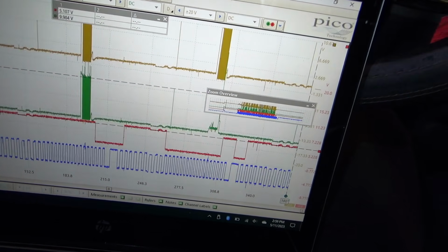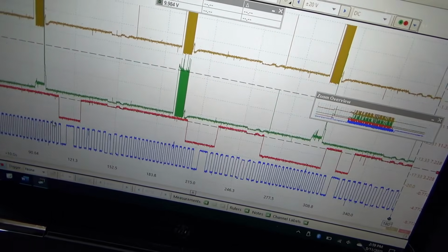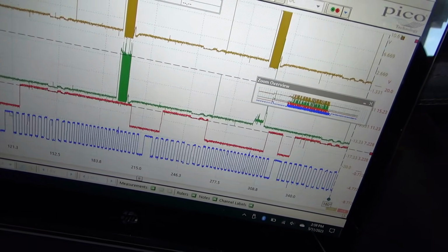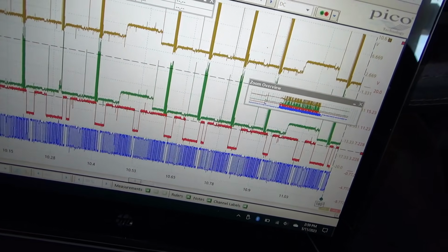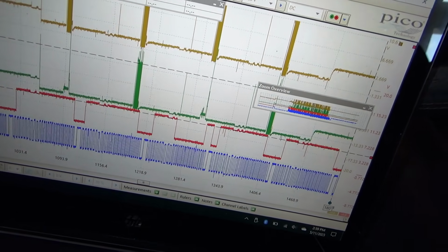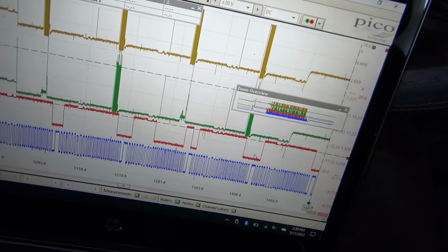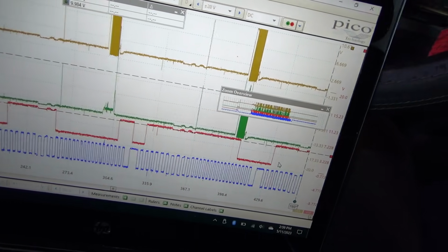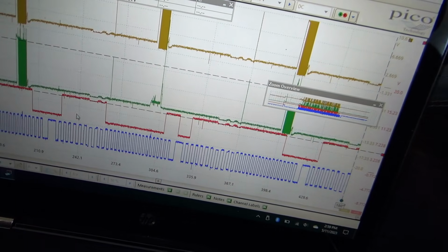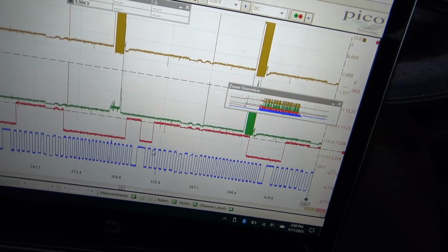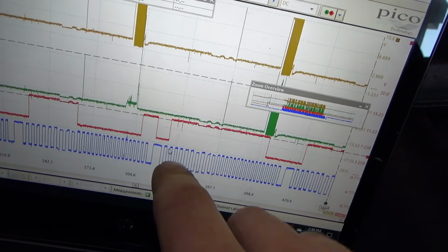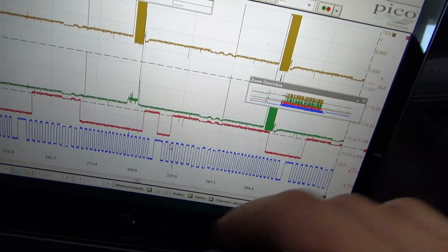So now all of the notches are exactly, or very close to, the sync pulse. Extremely close. Now maybe Volkswagen wants it to be rising edge with rising edge, like really close, because every time we shift these, it'll jump at least one tooth on the crank signal, which is quite a few degrees.